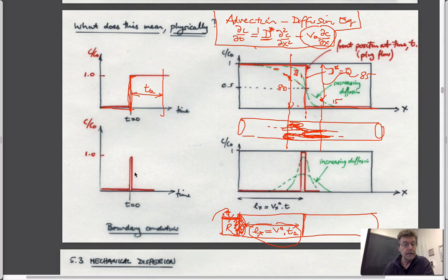It's a spike that you inject, and then you inject water afterwards at this upstream location. If there's no dispersion, then you'd expect it to look at a concentration of one just translating down the aquifer until it gets to the outlet at this point. If there is dispersion, so this is D equals 0, D star equals 0, and this would be D equals 1, as we said before, and 2, just different numbers. So that's it. So that's what you need to understand.